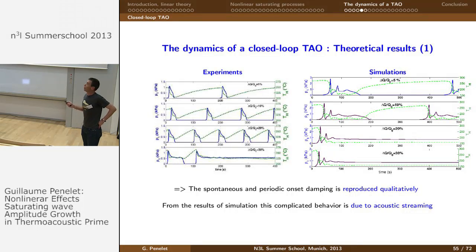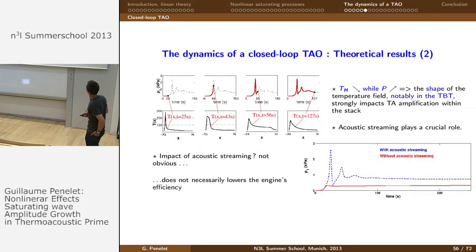Okay, so these are the results. On the left side, these are experiments. On the right side, these are simulations. So what we can see is that from the simulation, we can reproduce only qualitatively this switch on-off process of the thermoacoustic instability. And from the simulation, what we can say is that this switch on-off process is due to acoustic streaming. So let me explain this.